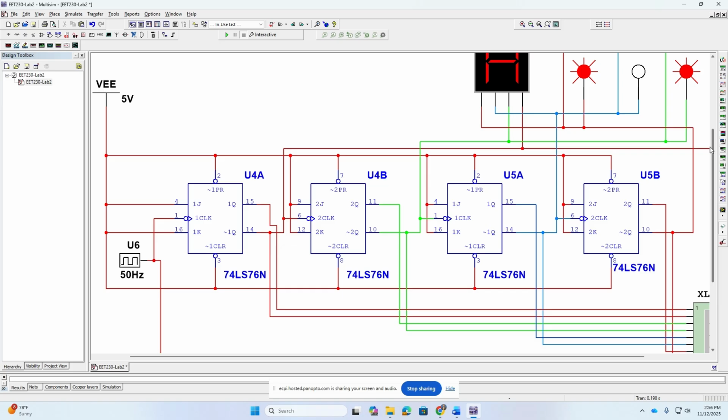What you're going to be required to do for the second part is not drive the clock of the second chip by the Q0. It's going to ask you to change it to Q, and that's the only thing you're going to do in the second part of the circuit to see what happens with the counter. Is it counting up or is it counting down? That's the kind of thing you need to figure out as you run the circuit and answer the questions.